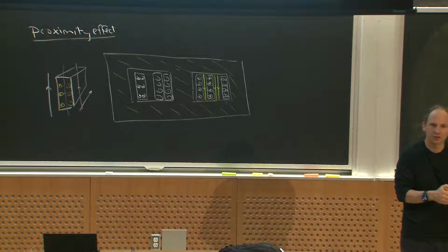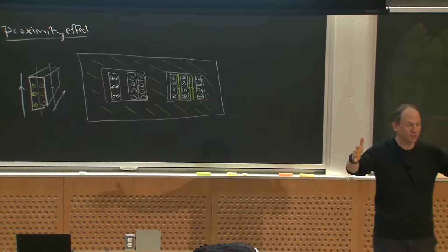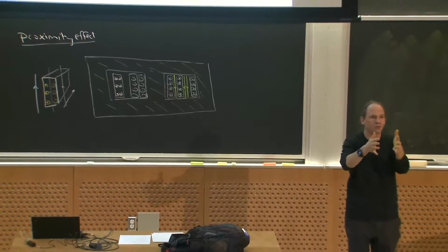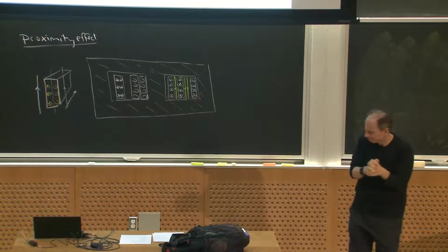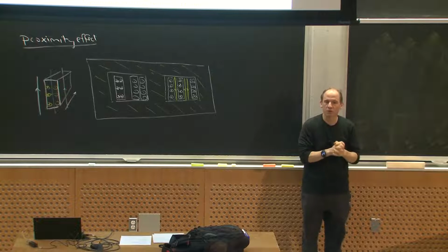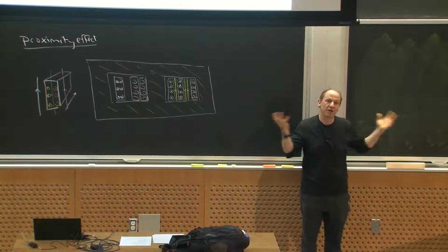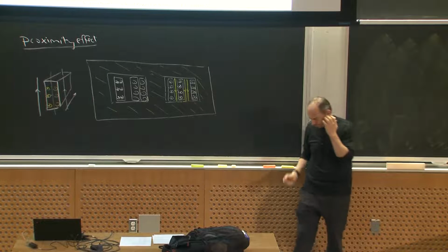Or you get into this weird situation, and so sometimes that forces you to use really fine wire, really small strands, even smaller than a skin depth. So think, you know, 0.3 skin depths might be what you'd get if you had a lot of layers, okay?